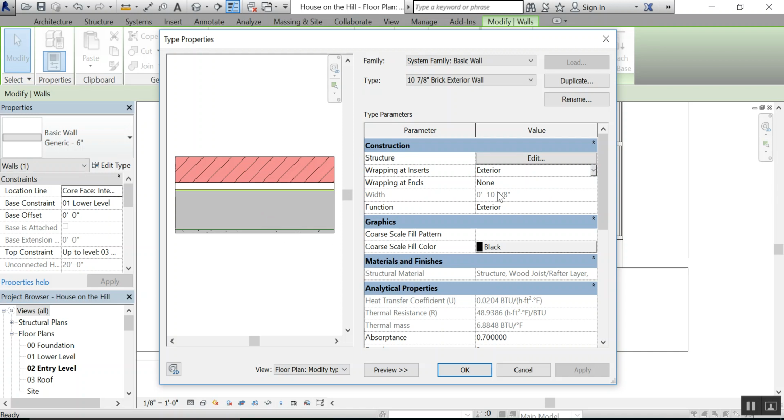We could have the exterior wrap around. We could have the interior wrap around that opening, the face of the opening, or we could just say both. We could have the brick and the gypsum board wrap around and meet in the middle of the side of an opening. And that's the way buildings typically are. So we're going to say both.